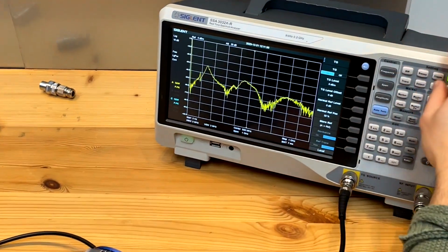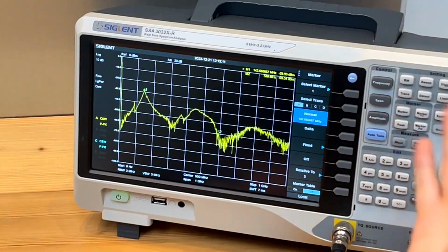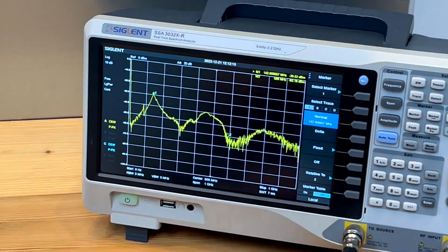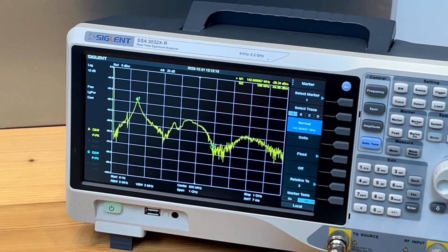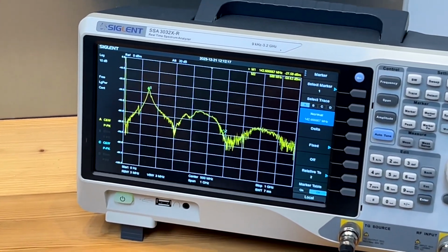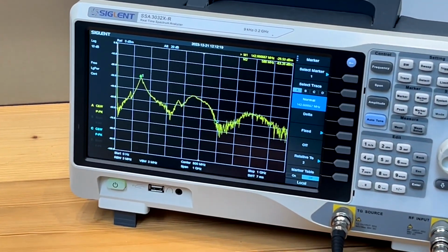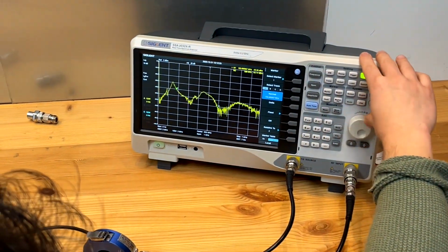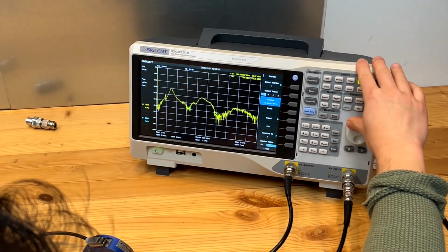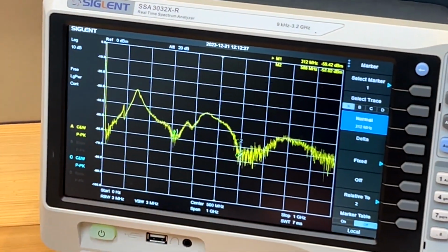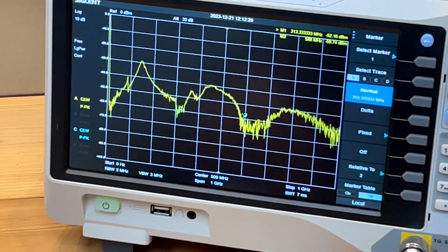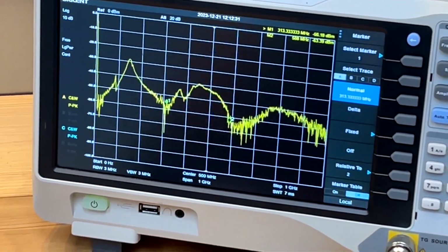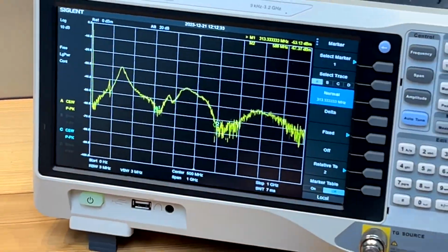At this point, which frequency is this? At about 142 megahertz, I picked up lots of current via this current probe. Whereas if you go to this point, which is 313 megahertz, I picked up a relatively small level of current, and then this repeats again.